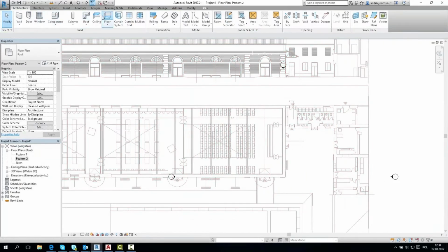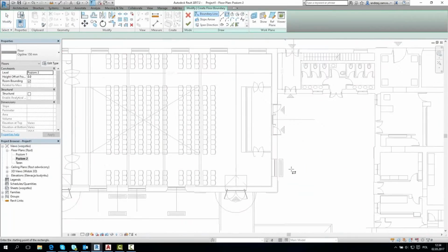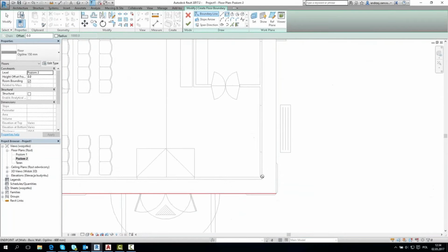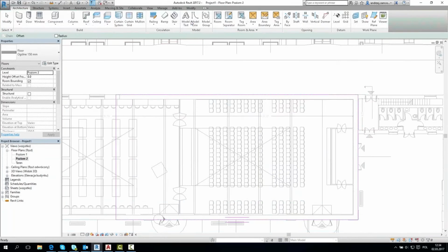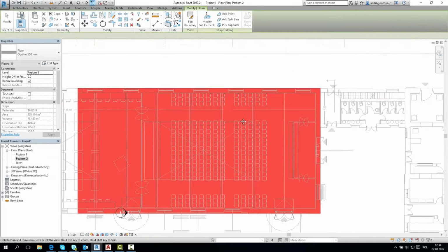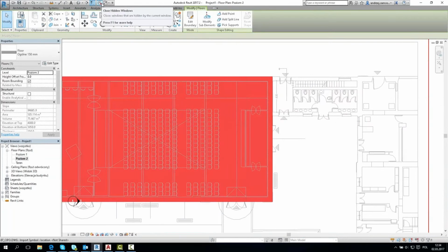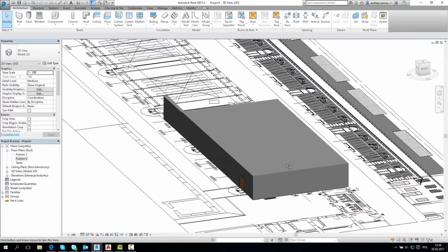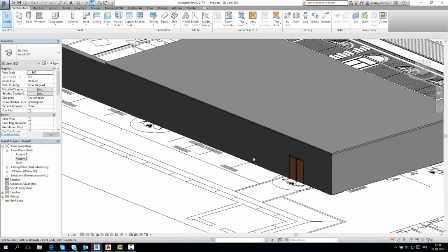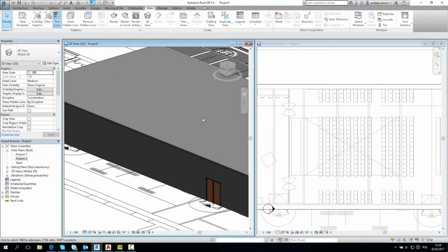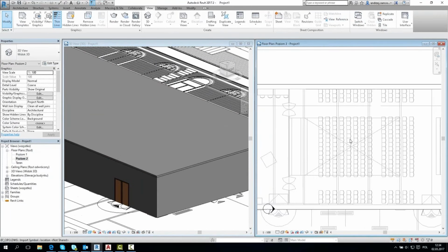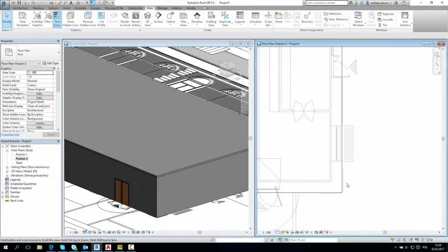So I'm in the next elevation, and I can create a ceiling, and very similarly, I can snap on the objects on the underlay, and I have a ceiling, and now having a look at 3D, my part of the building is done. So as simple as that is creating my 3D model.